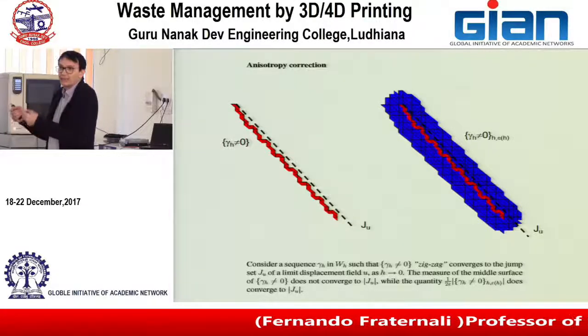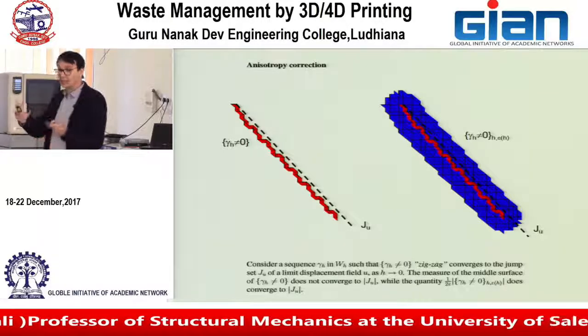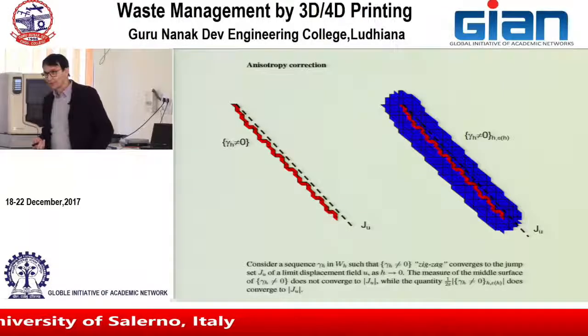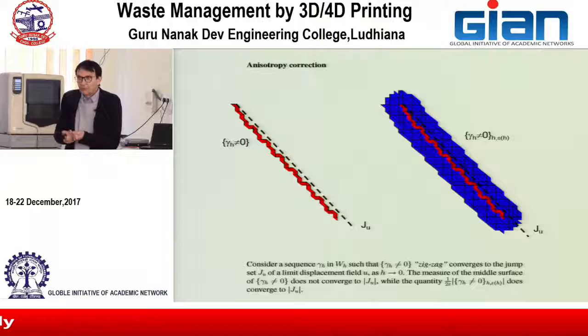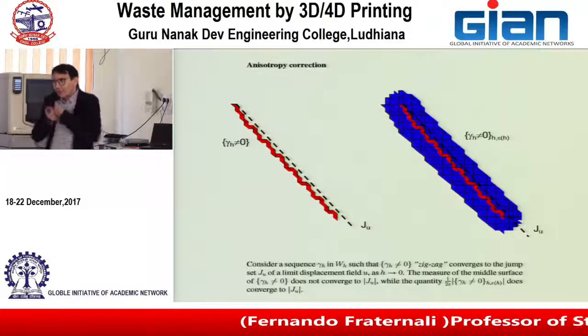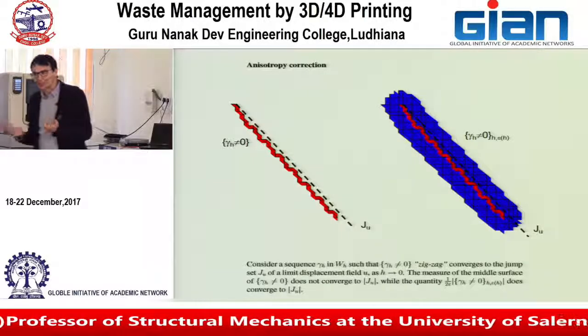And you get a different energy. This is the integral, I think it's a standard quantity computed by all the finite element codes. And then what do you have to do? You have to compare this new energy with the energy that you have spent to kill that element. Otherwise, it's always decreasing. Okay?